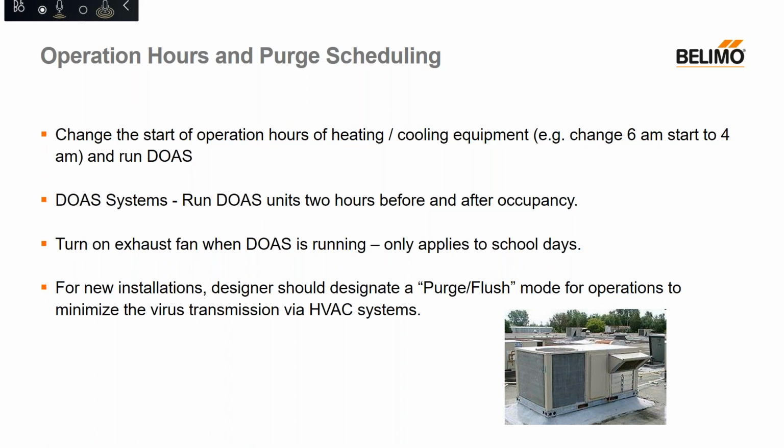Running your dedicated outside air systems 2 hours before and after is another way to get air change. It will be good to note here that the 2 hours before and after occupancy should factor in all those who enter your building. The last recommendation is for new installations.